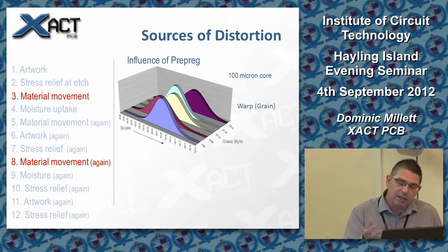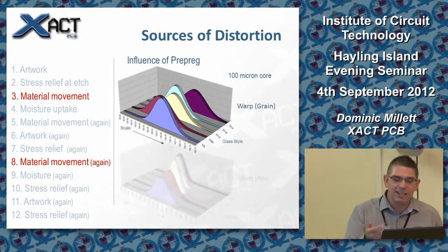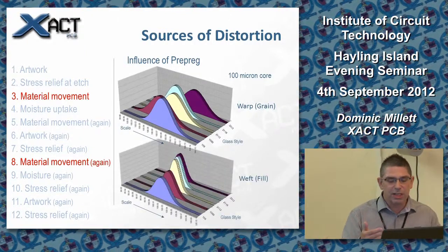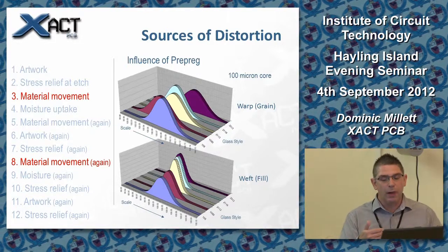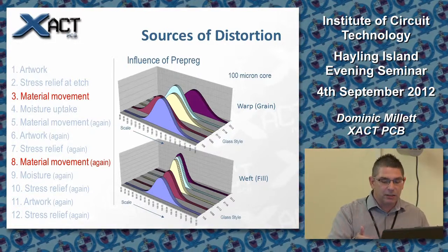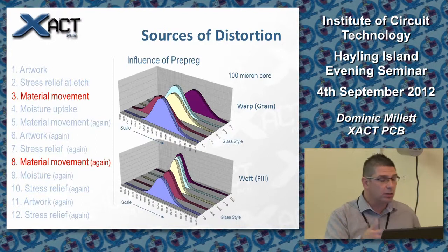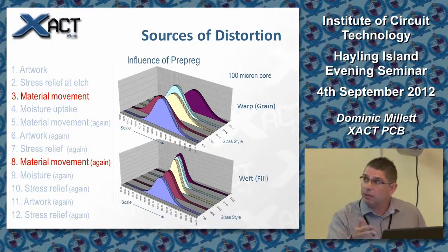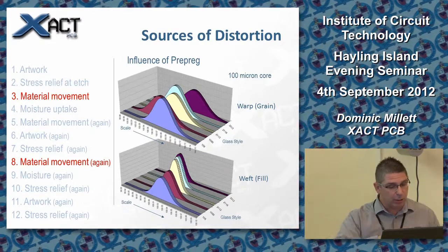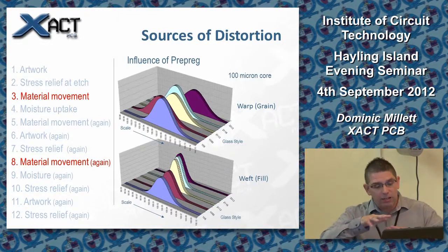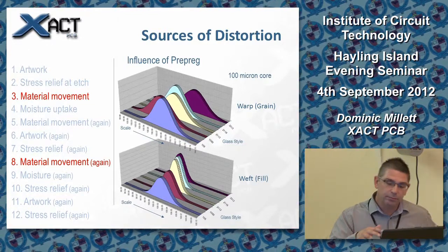Influences of prepregs. These slides illustrate the differences the different types of prepregs can cause. Different glass styles have significantly different amounts of movement, and the warp and weft directions I spoke about earlier are significantly different again.